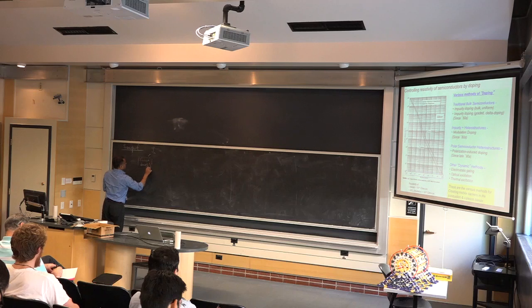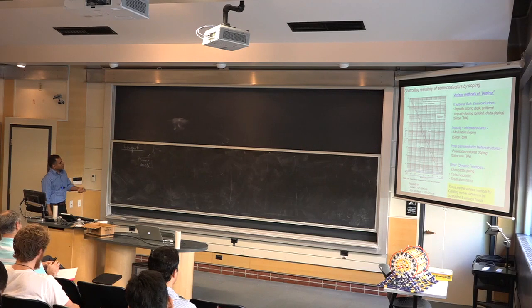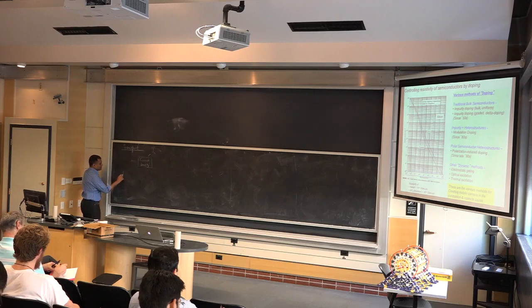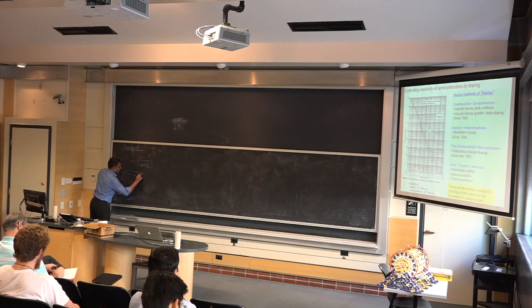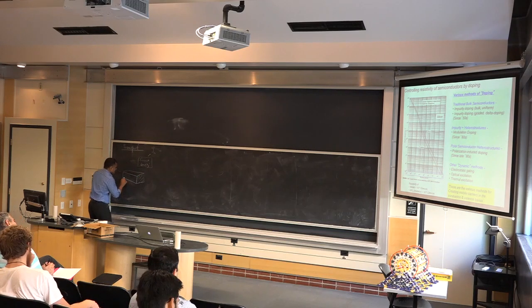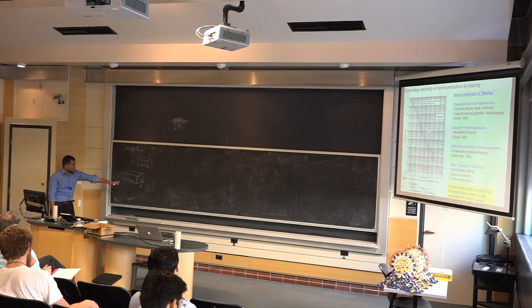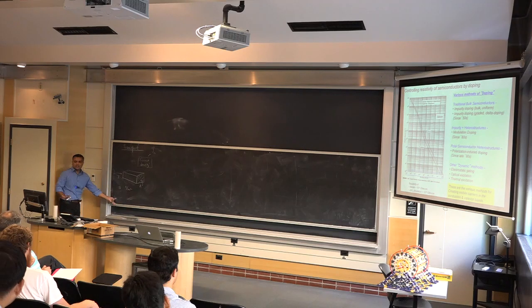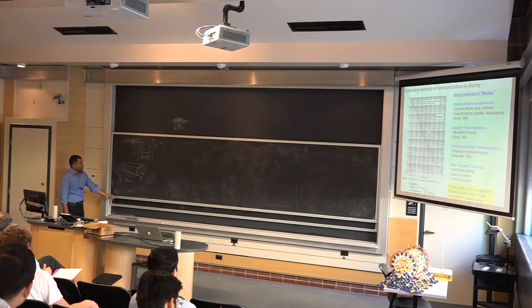And you can see very carefully that I'm not writing current, I'm writing current density, because as you can imagine, if you take a piece of three-dimensional semiconductor and ask how much current is flowing, that's not a very illustrative question, because I can make the thing bigger or smaller. Then the current doesn't have as much meaning as the density, which is essentially the current divided by the area through which it's flowing. That's for 3D. In 3D, your current density will be in amps per centimeter squared. This is the unit we use, some mixed units, not quite SI.